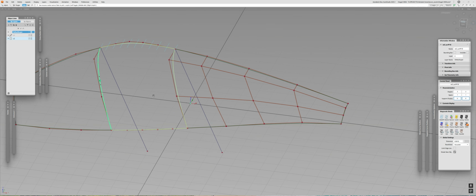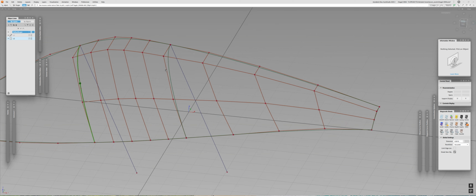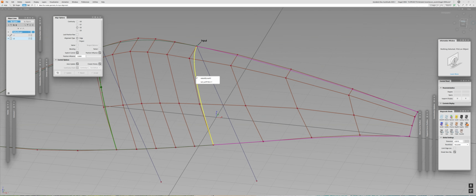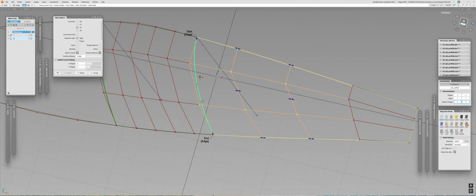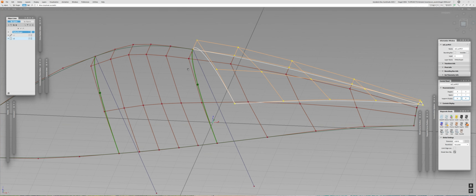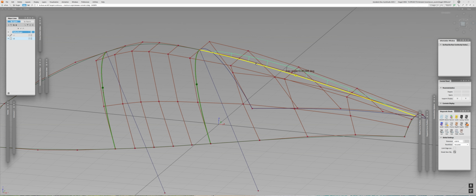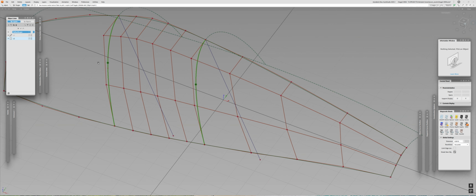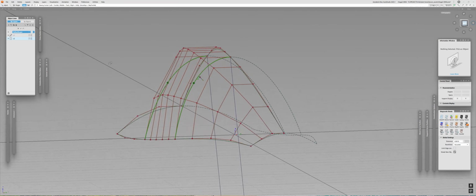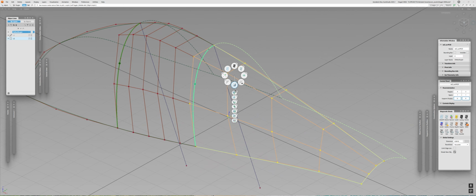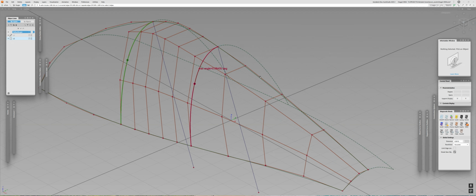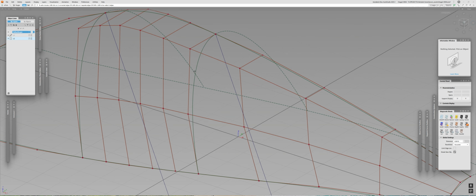All right, and then let me realign the surface as a curvature. Once again, position of line is supposed to be at 1. Okay, now let me quickly check. Did we? Yeah, we lost our continuity. So let me tweak this as well. So again, okay. So now we have a continuity, but now we lost continuity here on this edge.